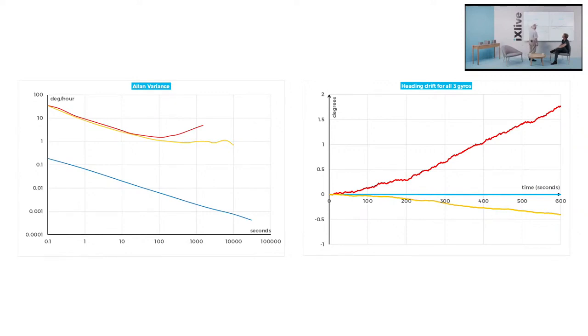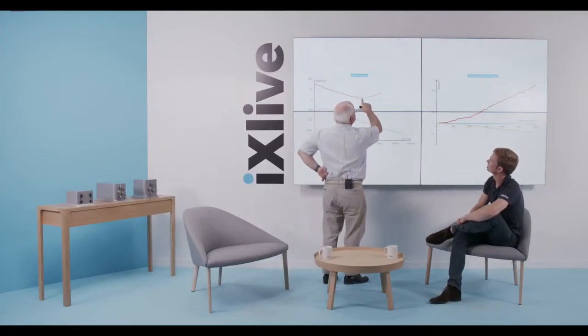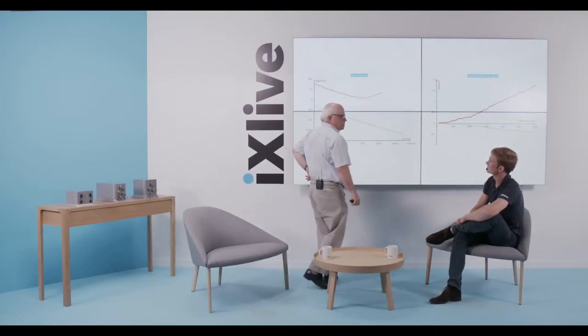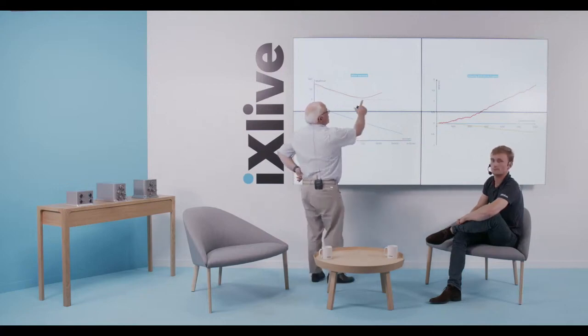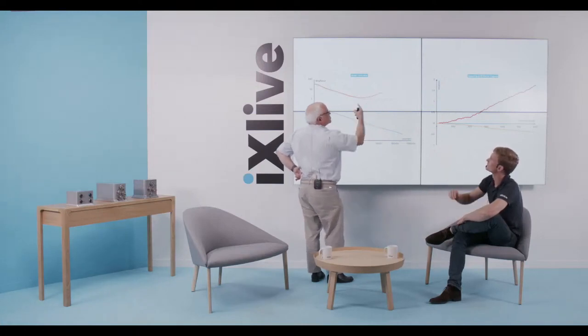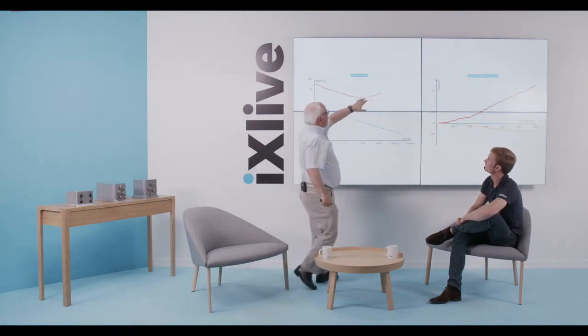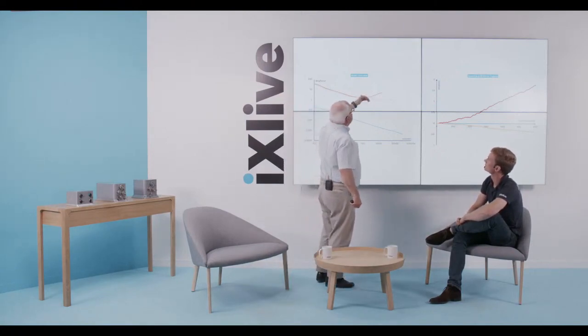You see here, the bias instability is the minimum value of this Allan variance curve. But what happens is that for this red gyro, the standard deviation of the averaging over time rises again. It rises quite a short time after you reach the minimum value.